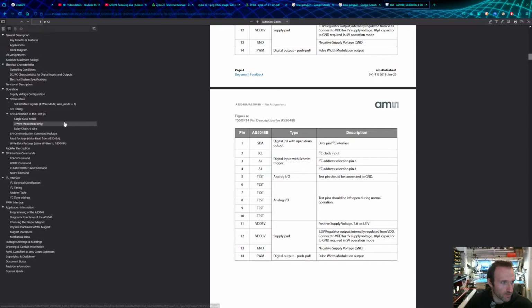The reason why I didn't want to use a gearbox though was because of backlash. There's play in the gears, and also you're adding more parts to the design, which makes it more complicated and more likely for stuff to go wrong, and more maintenance if a gear breaks or whatever it is. So I just thought it'd be interesting and cool to do something like a direct drive.